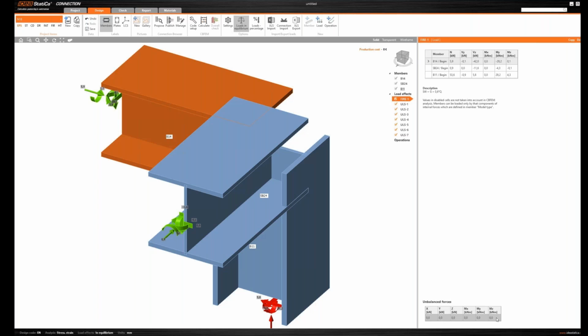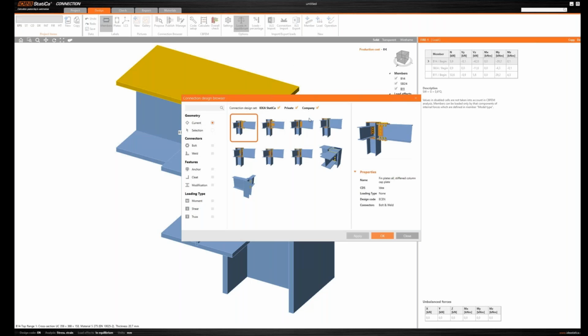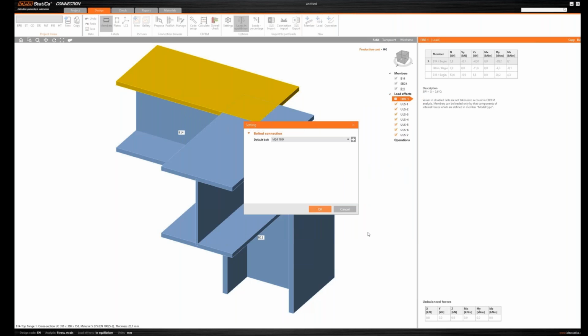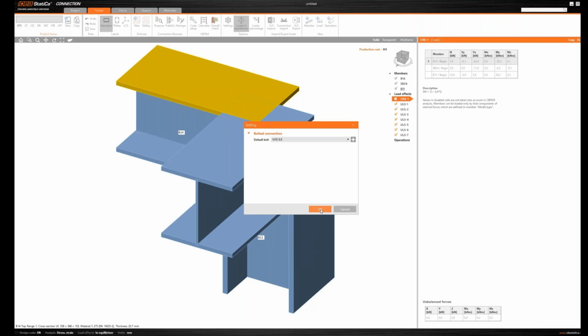Before we proceed with the actual fire design, I must connect these members and make sure that the node works under the ultimate limit state load. So for this check, I will deactivate the fire combination, and then I will move to our templating system called the connection browser, where I will open it and apply this template I have created. And here I will pick an 8.8 M30 bolt, apply it.